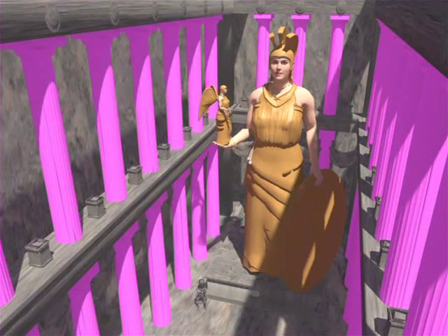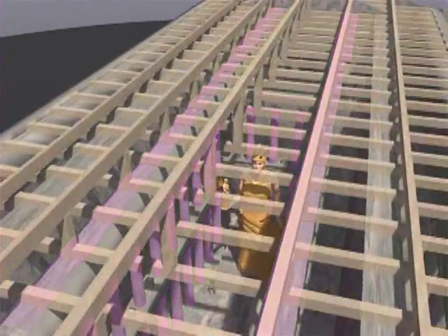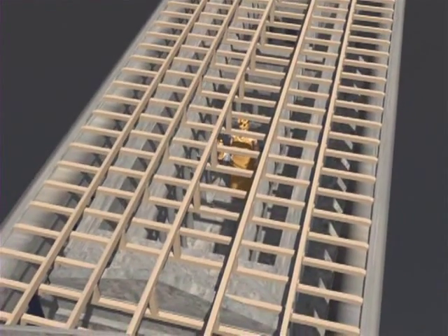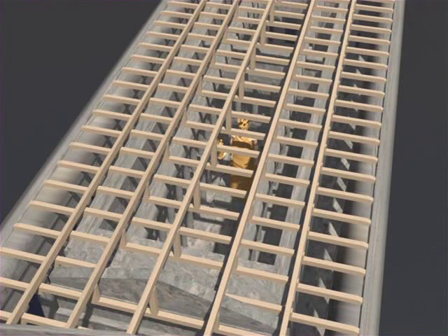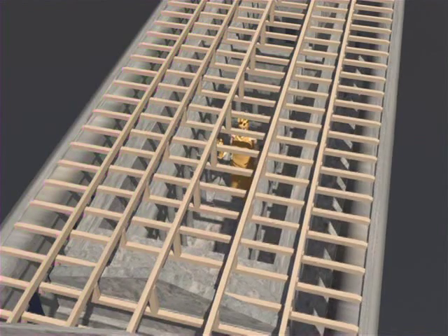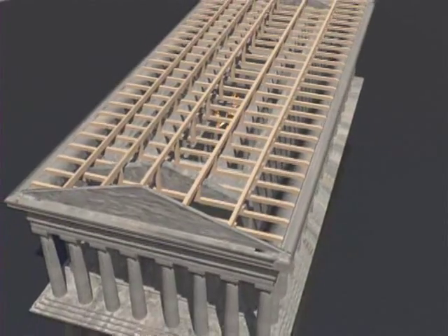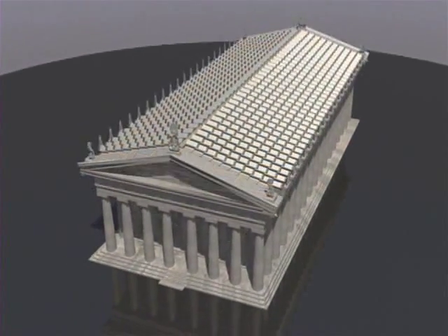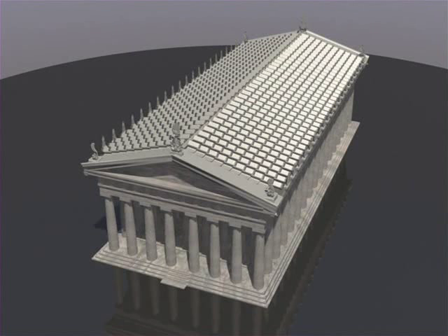Based on this arrangement, each transverse roof beam actually had 5 short spans, as you can see here, from outer colonnade to cella wall, from cella wall to inner colonnade, then across to the opposite inner colonnade, to the opposite cella wall, and then finally to the opposite outer colonnade. It's clear that the sole purpose of these inner colonnades is to support the roof. Had the Greeks discovered the truss, there would have been no need for these inner supports because the roof trusses could easily have spanned all the way across the cella.